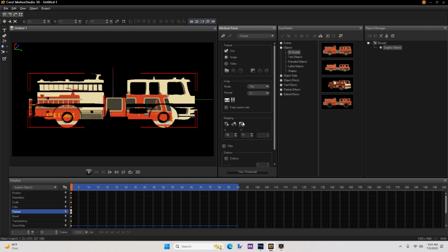And this tool here enlarges everything. You're going to have these same props down here. It's these codes, numbers. Z is depth, Y is height, and X is width. So over here that would resize your texture map. This one rotates your texture map. We don't need to do that because we want it to be level with the engine here. And this one here will move it. So you click on that one.